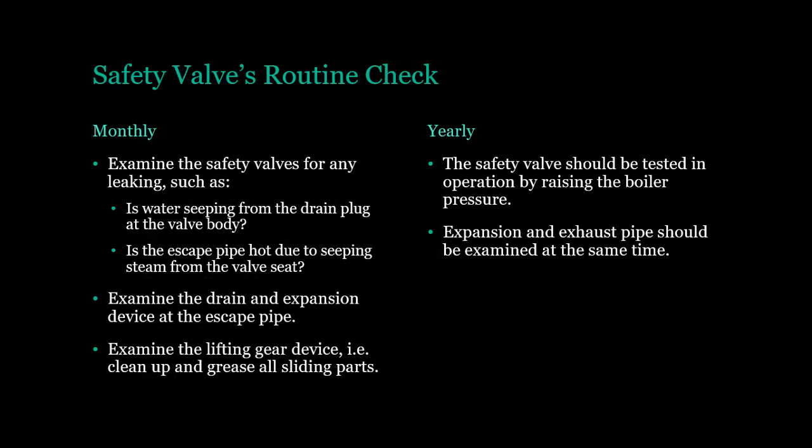Safety valves routine check. Monthly, examine the safety valves for any leaking, such as, is water seeping from the drain plug at the valve body? Is the escape pipe hot due to seeping steam from the valve seat? Examine the drain and expansion device at the escape pipe. Examine the lifting gear device, i.e. clean up and grease all sliding parts.